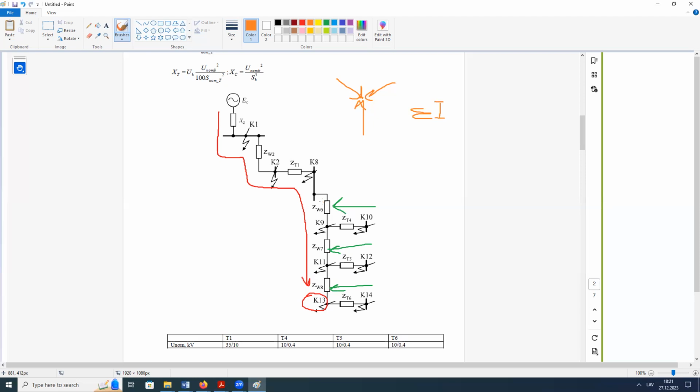It is minimum okay. If it is not equal, what is the solution for the next step? It could be equal or above. It couldn't be less than 1.2. If it is less than 1.2, it means that we can't be sure that it will be sensitive. We are not sure that the protection is sensitive, so there is a possibility that protection will not detect the fault.